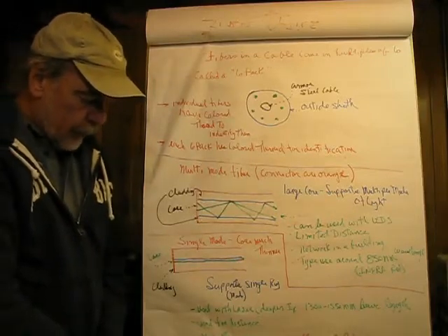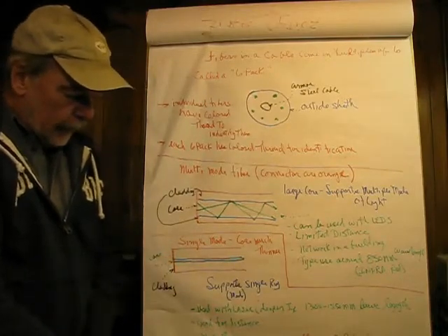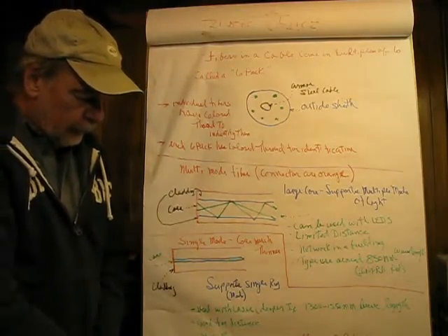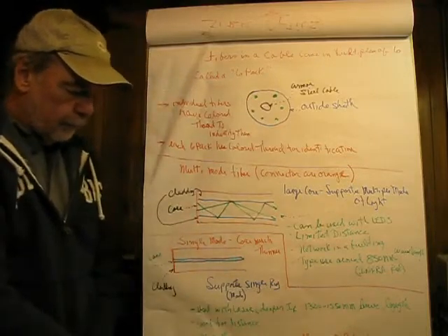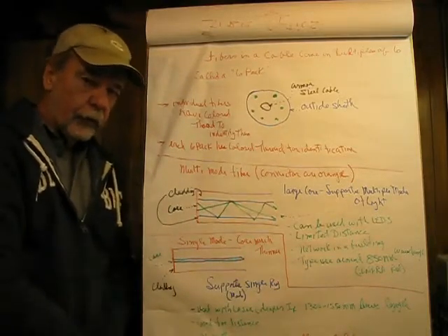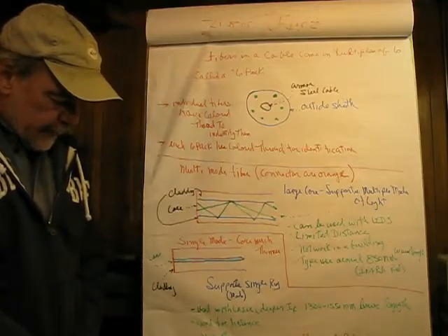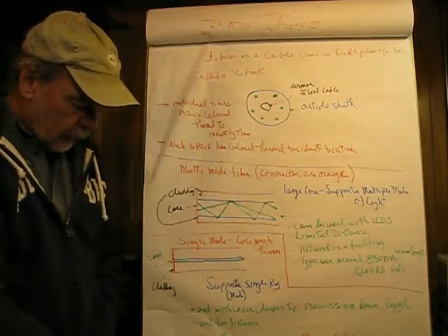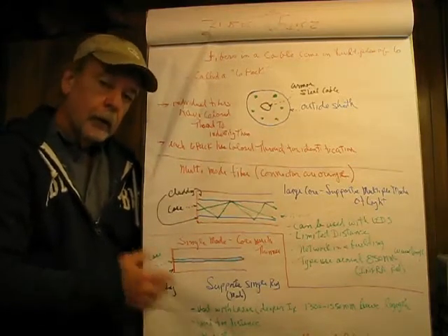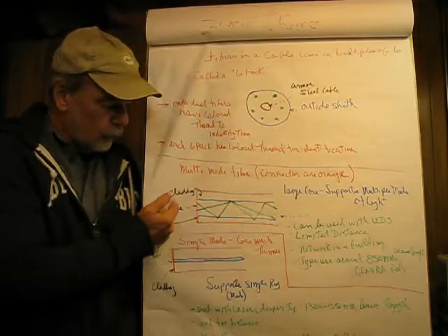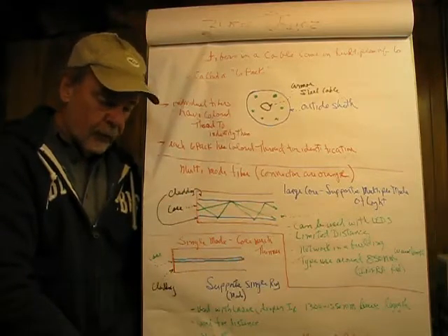It's used with lasers. It has to be very carefully coupled. And the wavelength of this sits around 1300 to 1550 nanometers. So it's lower in frequency than multi-mode. It's good for long distance, and of course it costs more, which is the reason why multimode is used in establishments where you do not need the distance.